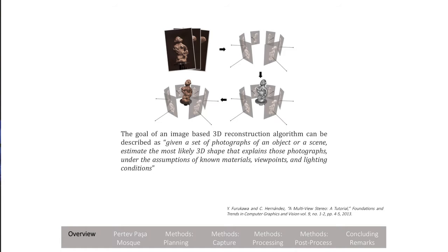But it's also important to note that the accuracy of this final three-dimensional model is only as good as the quality of your images and the number of images that you use. So if you're using a cell phone and you can only upload maybe 40 photographs, you're not going to get as accurate a result versus some of the software that was mentioned earlier, which has, for practical purposes, no limit to how many photographs you can upload. And the level of detail you can get is obviously relative.